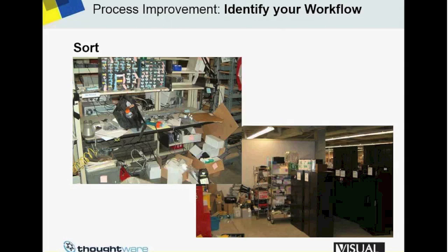For each assigned area, individuals should clean the equipment and tools, the supplies and workspace, identify sources of dirt and spills and leaks and mess. We should tag equipment to identify these sources. Think of ways to maintain cleanliness and look for ways to prevent reoccurrence. Things like splash shields, repair leaks, repair hoses.